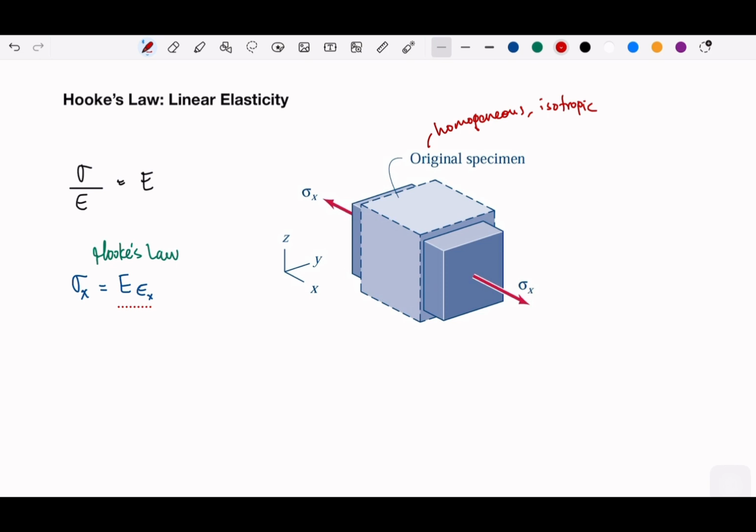For example, if you stress this, maybe in the real world these have different crystalline structures, and maybe they have some weakness, and maybe some fracture that we did not anticipate, right? But in our design, to make the mechanics calculation easier, this will be simplified, and we say, okay, it's all homogeneous, maybe it's steel or another material, and it's isotropic. So we don't really care about different crystal orientations. Okay.